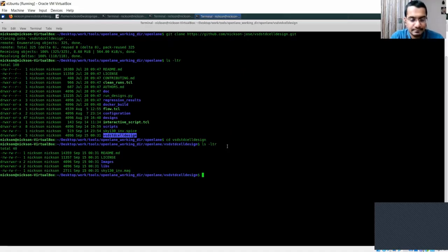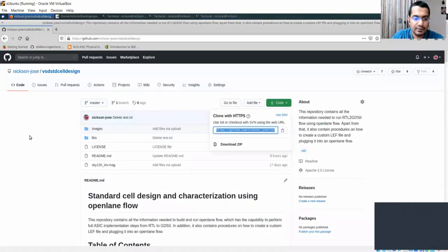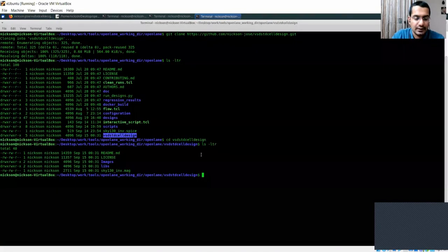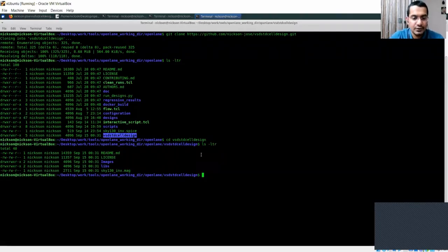Let me jot it down. For a value of WP by LP equal to WN by LN, this is the rise delay and the fall delay that we just calculated. It's 148 picoseconds for the rise delay, and the fall delay is 71 picoseconds. And you draw a 45-degree line from 0, and this is the point at which it intersects. If you zoom in over here,